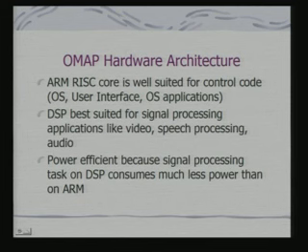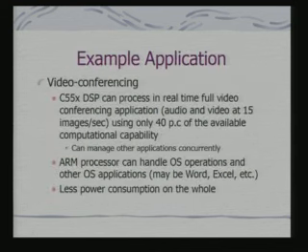And what has been found also through benchmarking studies is that this combination, that is of mapping signal processing tasks onto the DSP and the OS onto ARM, is power efficient, because a signal processing task on the DSP consumes much less power than on ARM. And in fact, if required, you can even use ARM's signal processing capability.